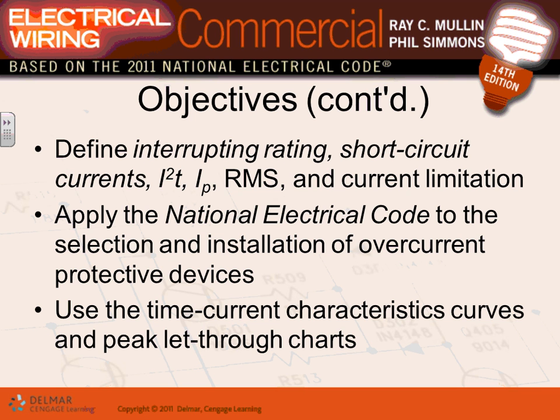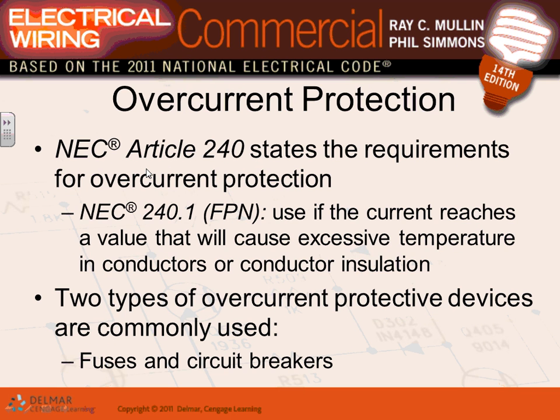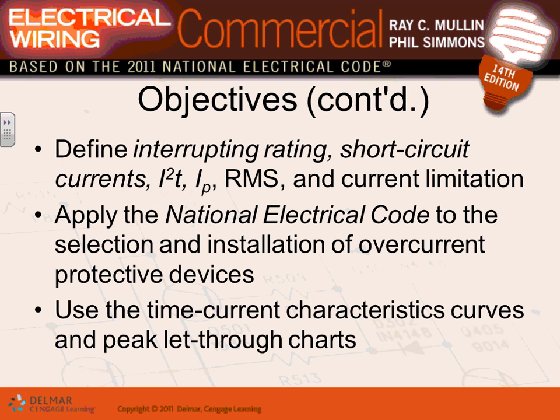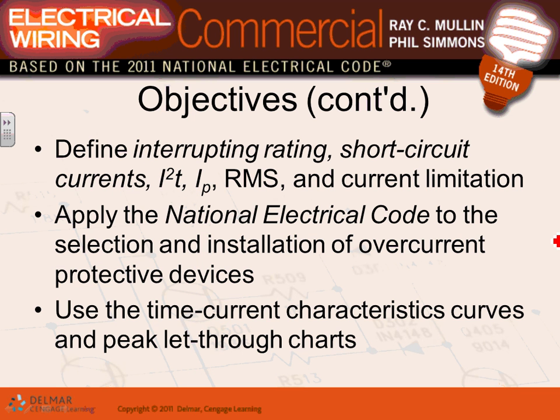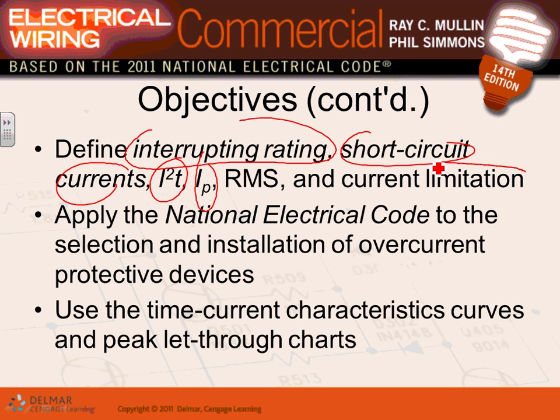So we're going to be talking about short circuits. With this comes a very important concept, which is interrupting rating. There's something called the interrupting rating. Let me go grab my pointer here. There you go. So we have my interrupting rating right in here. We have the short circuit current. We have the I squared T, the energy, the I peak, the magnetic force, current limitation. All these concepts are related to interrupting a short circuit.